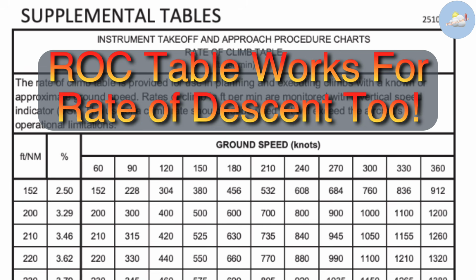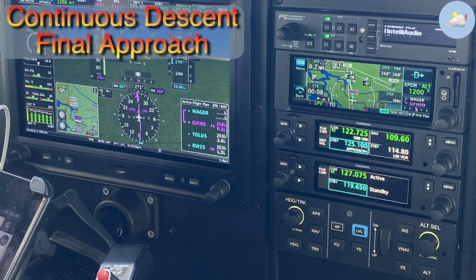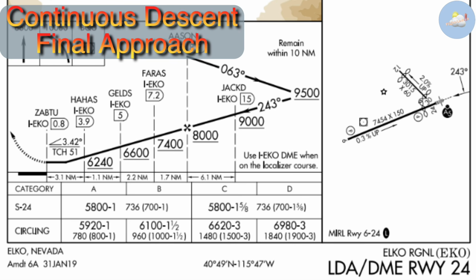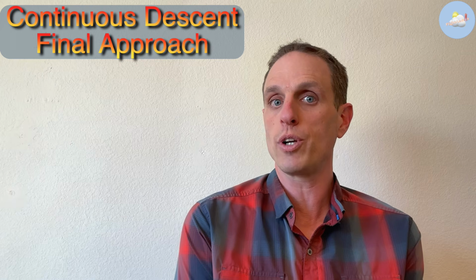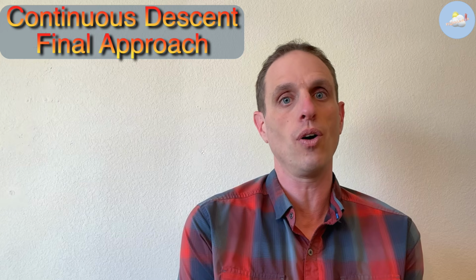Now, the key to doing this, whether in a fancy GPS-equipped plane or a conventional style avionics plane, is you still need to comply with all of your minimum altitudes along your non-precision approach. You don't get to just completely ignore those and continue descending. We're just following this concept of doing a continuous descent all the way down. At the same time, having a fancy gee-whiz GPS calculate your continuous descent angle is a pretty nice feature.